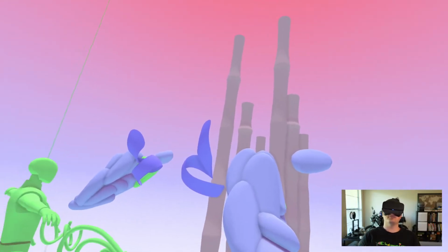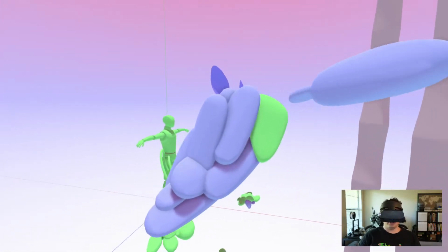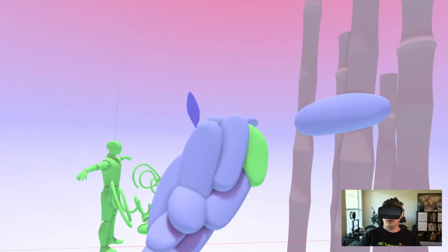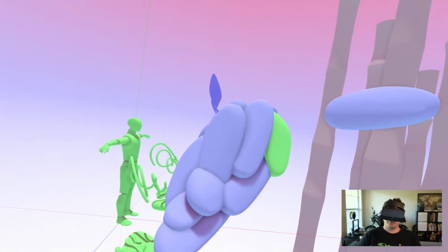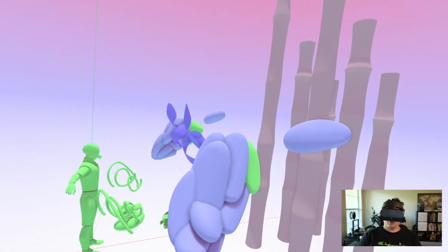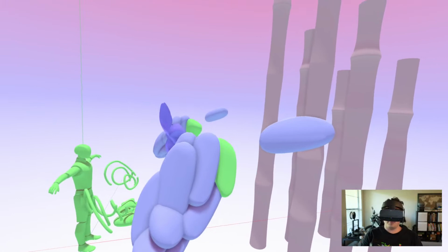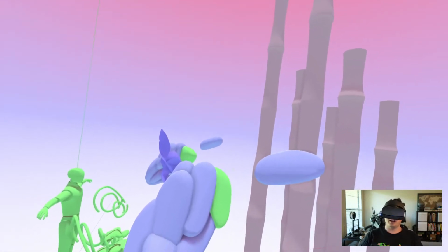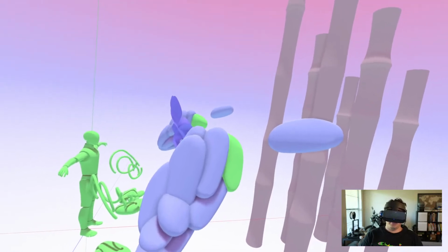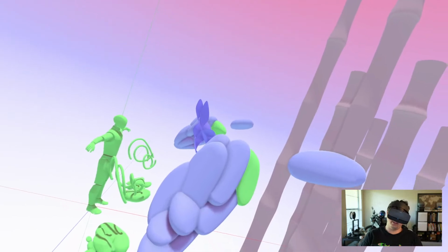I did wonder if there's a way to sort of fake a Boolean operation in Gravity Sketch for display purposes without it actually doing it physically, geometry-wise. But the only problem is if you have a bunch of Booleans and a bunch of things cut up and the Boolean is really integral to your design, it might become an issue when you want to export, because eventually you're going to have to calculate it.